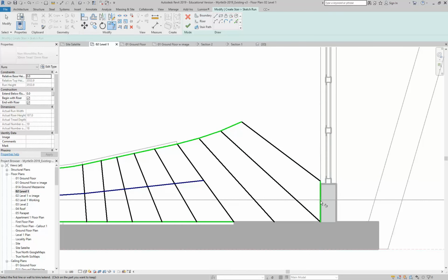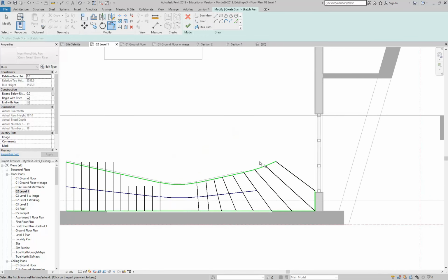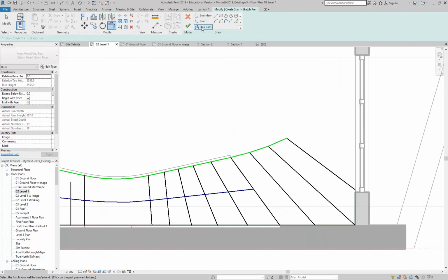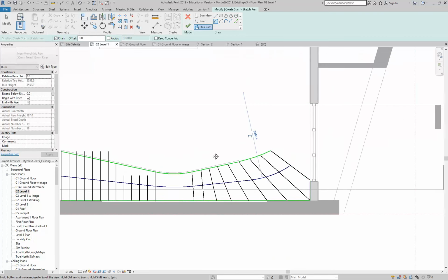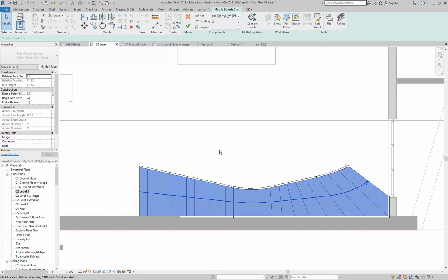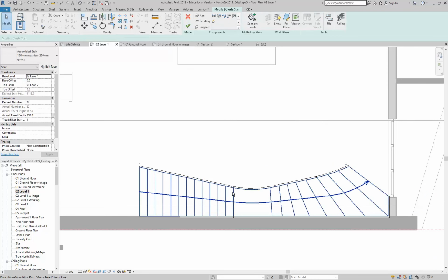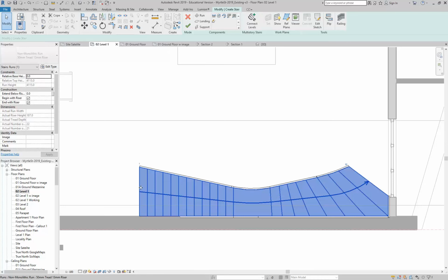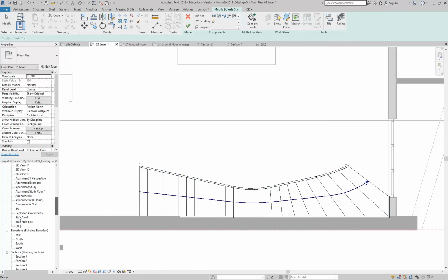And then I'll trim these things together. And that should work, except again I've forgotten the stair path like I always do, so I'll just draw that in now. And again, maybe with a curve. Yep, that should be good. Okay, so again, finish, and it's all working. So you can usually make any sketch you want work.